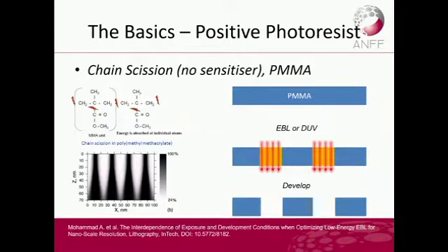The third type of photoresist is a transition resist. These are usually primarily used for deep UV or e-beam lithography. So think about your polymer film as PMMA, polymethyl methacrylate in this case. If you shine deep UV or electron beam light to the resist, it's going to start cutting these polymer chains. These polymer chains are very easily cut with about 2 to 5 electron volts of energy.